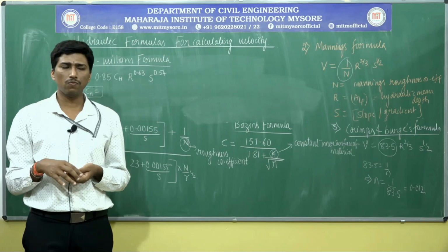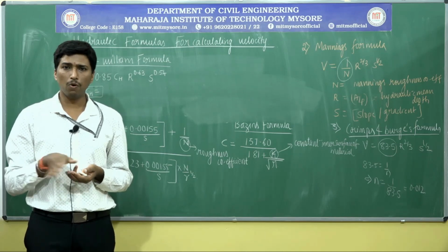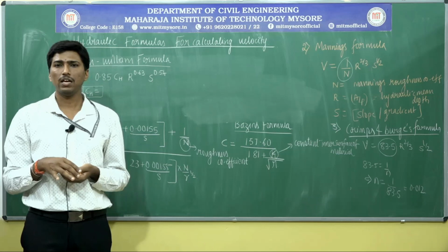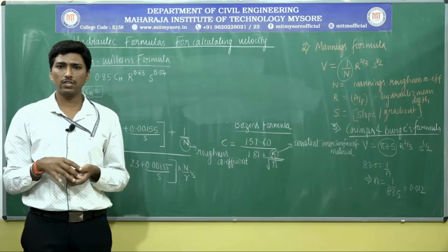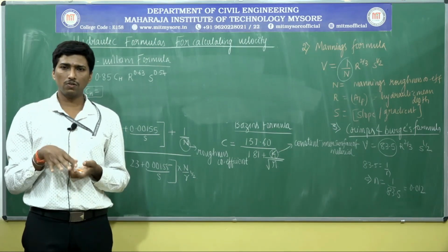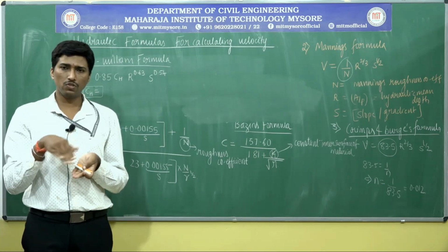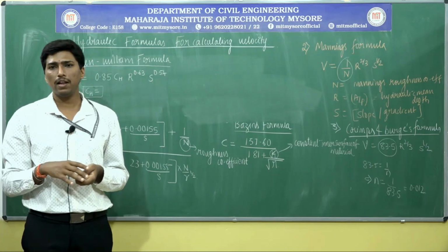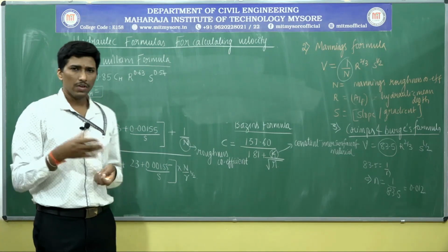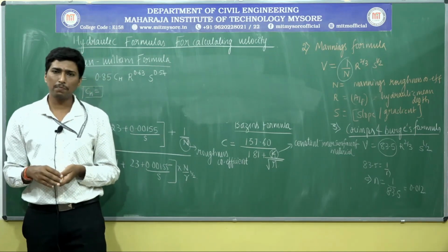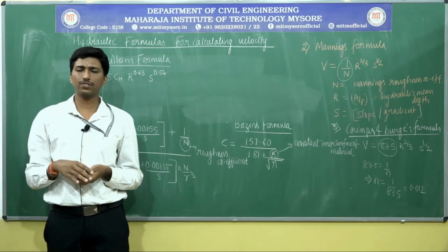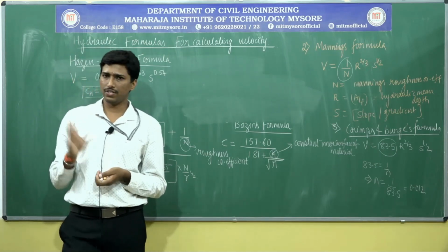Therefore they go for using vitrified material at the bottom portion, especially for the pipes, to see that during non-scouring velocity conditions, in the maximum velocity cases, the abrasion caused should be minimal in nature. In the case of plastic pipes, I think sir has also discussed in the previous part on sewer materials.